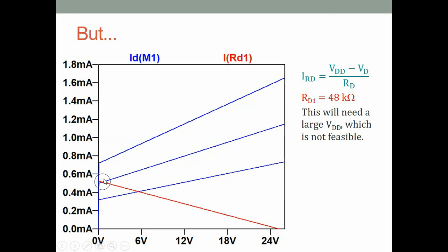Okay, a point on the side, there are of course integrated circuits that can operate at much higher voltages, 60 volts, 100 volts. MOSFETs, I should say, and integrated circuits both. But these are special purpose MOSFETs. They have very thick oxides, and they have to be designed such that they can withstand high voltages and don't break down.